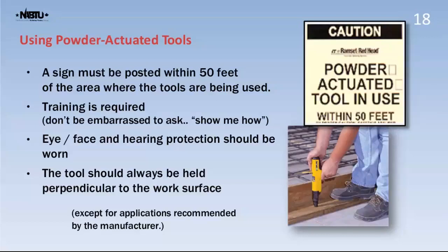The tool should always be held perpendicular to the work surface. You can see the picture over here. The guy is holding that perpendicular to the surface as he shoots a fastener for that board into the concrete floor.